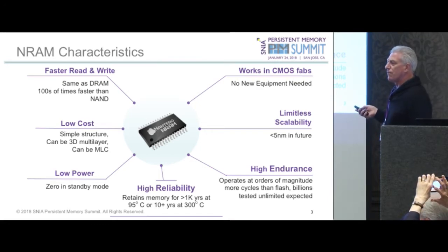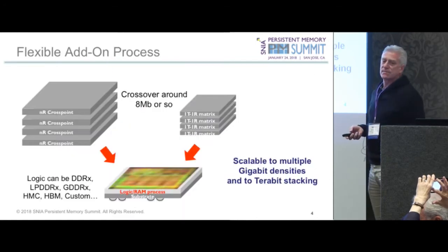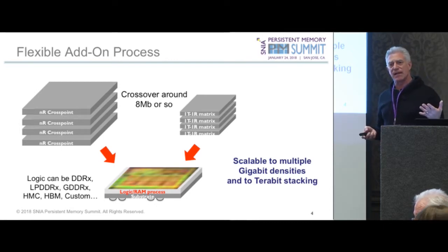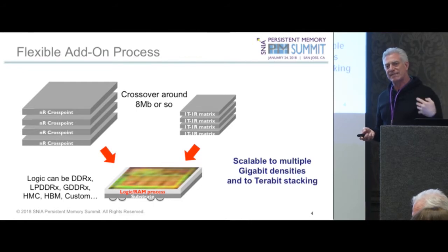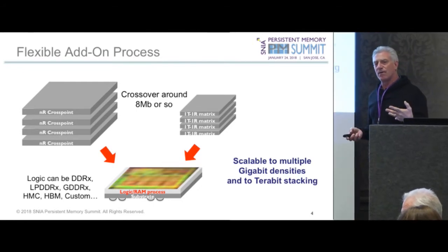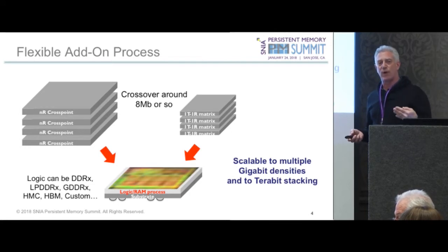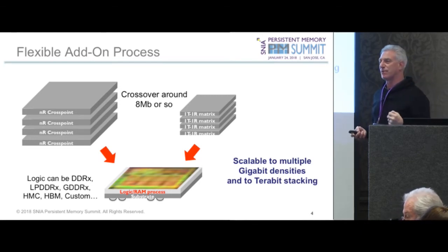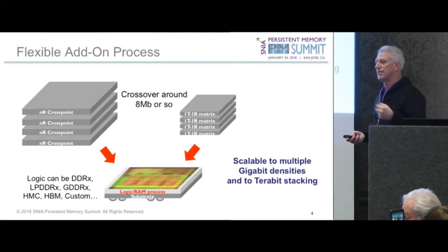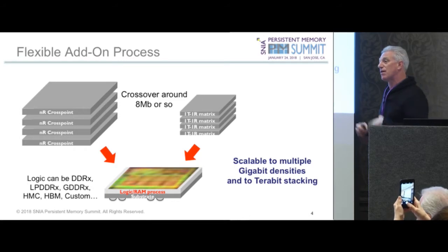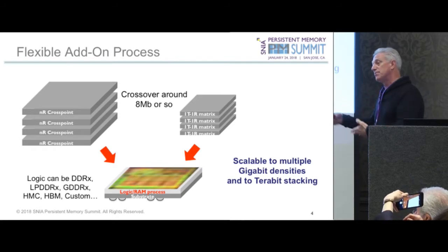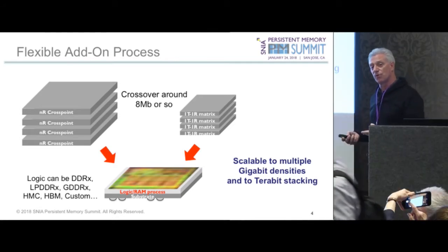But what problem is this going to solve for us? Well, there's a couple of problems. One is you have to think about what is the definition of persistence. Persistence means that when power fails, the data is going to be guaranteed. And we've looked a lot at, for example, what happens when you have a bus transaction. We saw a presentation today where the NVDIMM-N, on power fail, is going to back everything from the DRAM up to NAND Flash and then restore it after power is restored. We also saw another architecture where the contents were stored on the memory channel and had to be moved across the memory bus over to another module for the backup.